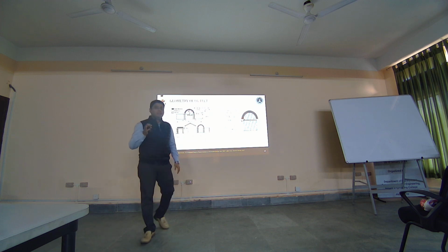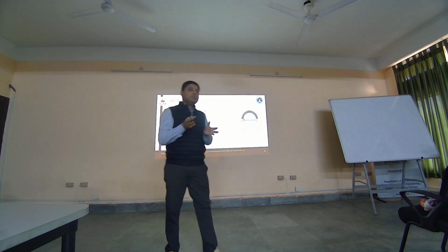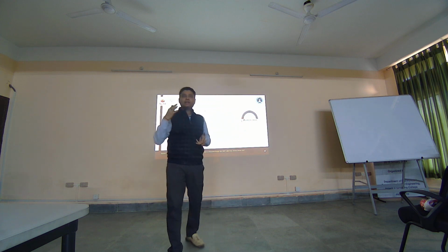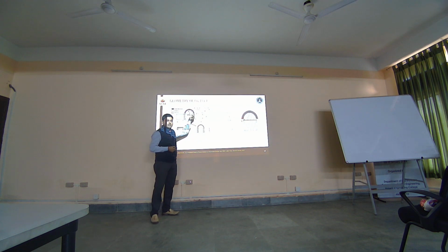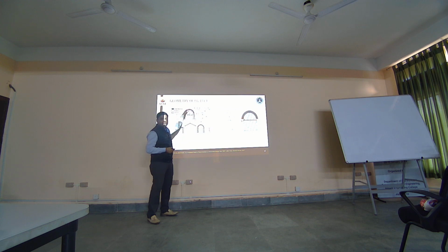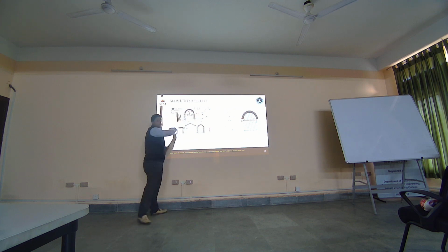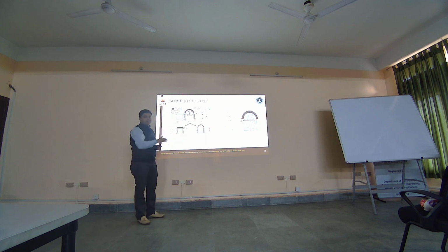tried to model it. Now, for a very conventional structure, you already have lots of papers, articles and insights. But no one had done this kind of architecture where you have a circular variation of the vertical electric field. If you observe towards here, the thickness is small. This entire semicircle is the oxide. Here the thickness is less. As you move here, it starts increasing, and again it starts decreasing on this side. So this is the nature of this entire electric field profile.